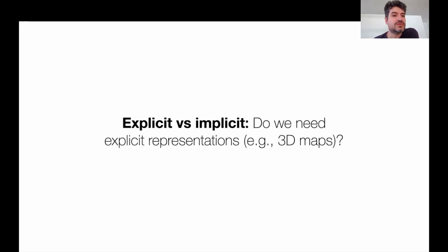So if you want, for example, to render or train 3D maps, which is an extremely important characteristic for SLAM and 3D reconstruction for robotic perception purposes, this is something that's really hard at the moment. And with a traditional explicit representation that you can obtain through volumetric mapping, TSDFs, surfels, and so on, you get the other pros and cons.